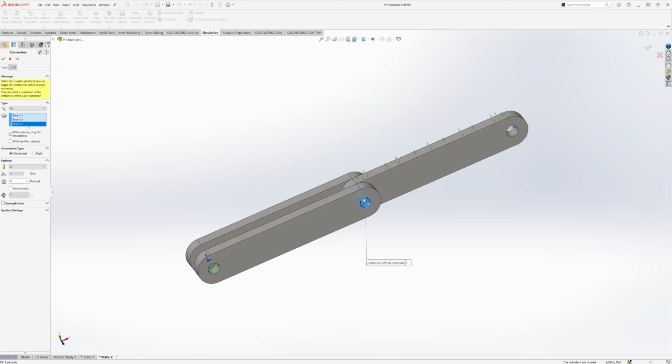or you can do it with no rotation, but most times like with a key, which means it just has a little notch you've probably seen on gears and different things, which means it won't be able to rotate. And again, in this case, I'm not really dealing with any rotation here, so it really doesn't matter too much. I'll just leave it with the retaining rings. It's not really going to matter too much in this study, but you can play with these. Sometimes you can avoid having to do some other fixtures depending on what you do here. That's how you can do this.